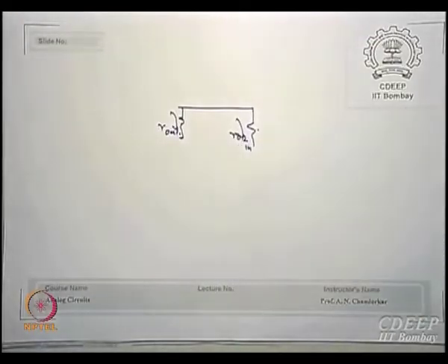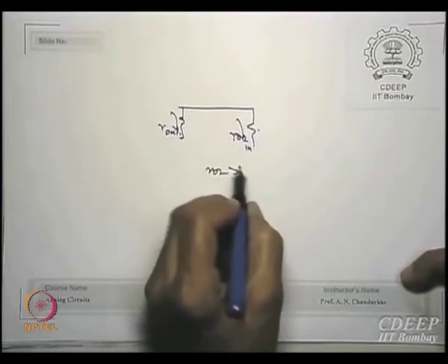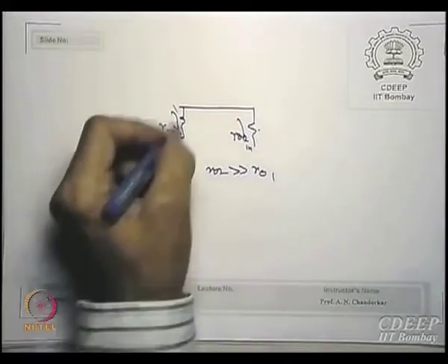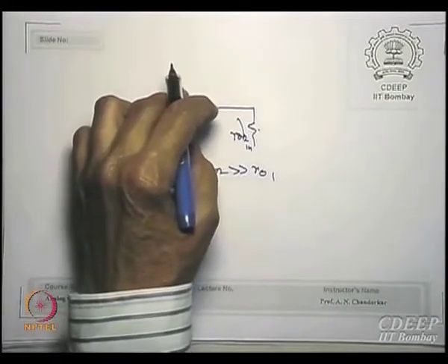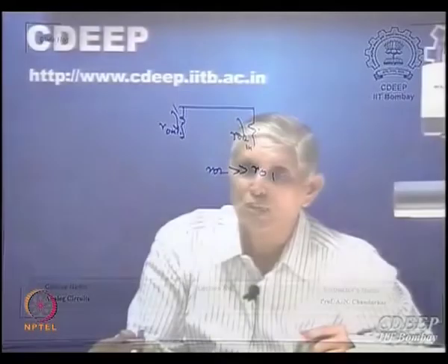Okay, what is it called? Essentially the net resistance will actually reduce and therefore the voltage at the input will not remain the voltage which you were feeding, is that correct? So what should be ideally, R in 2 should be much greater than R out 1, then what will happen? All the current is only here, so this voltage remains constant, so the next stage sees the same output of its first stage, otherwise it will get modified. And what is that word in other circuits called? Loading. The next stage starts loading the first stage, is that correct?